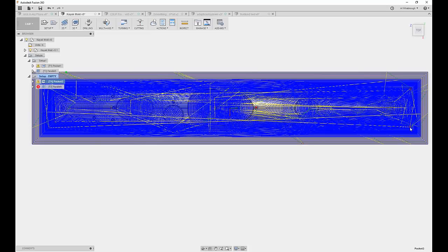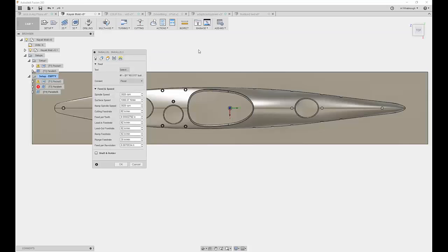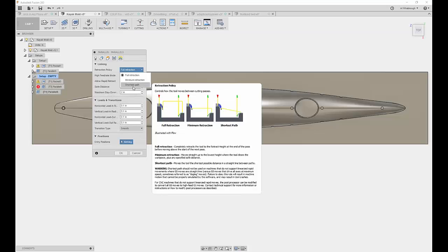We actually have an option in the Haas post that's on by default to force rapid movements into high feed rate moves so that we know where the tool is going to go. And especially when you're down in the pocket, you wouldn't want to use a rapid because then if it does dogleg, you're doglegging into the part. It's something that can happen if you turn that off and you're using our 3D operations. In the 3D operations, we have this shortest path linking, which finds those rapid movements through the part like that, and it can catch you by gouging into your part.